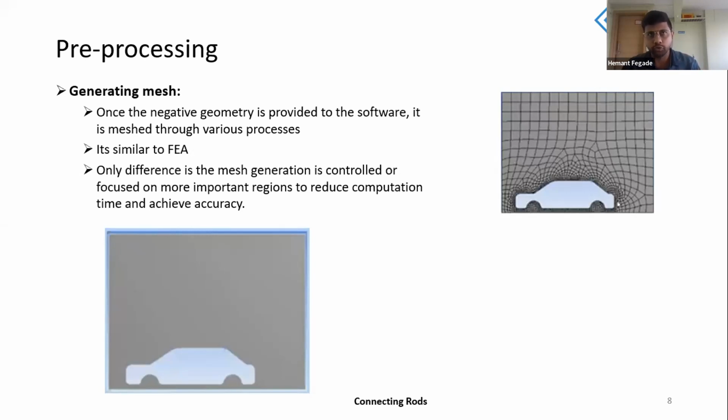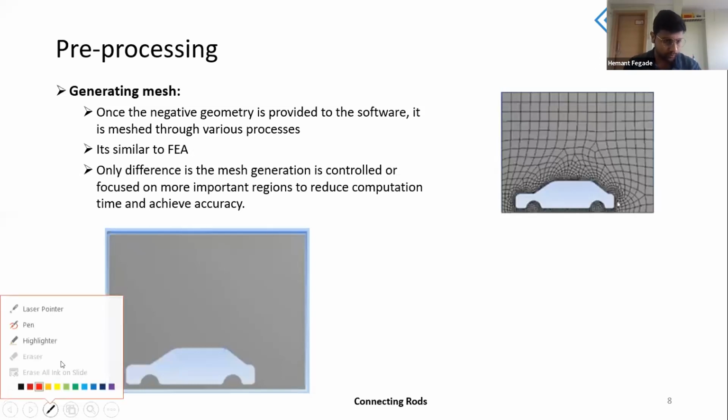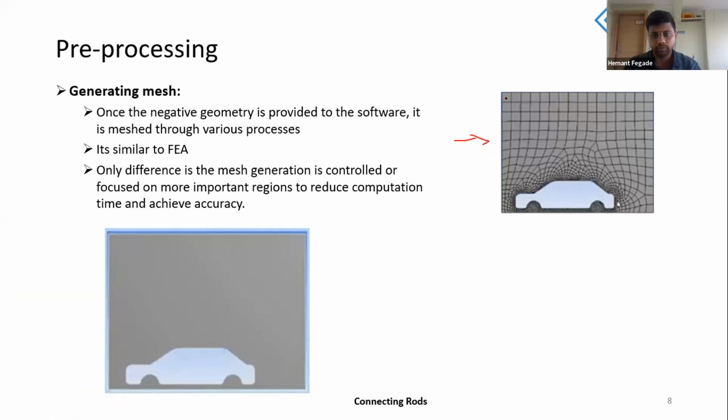small elements. So it will do two things. When you divide a particular model into these small squares, all of the properties of the fluid moving past this point are captured. In this case the air is going to be blown over from this part, so this line is going to be its inlet, this line is going to be its outlet, right?